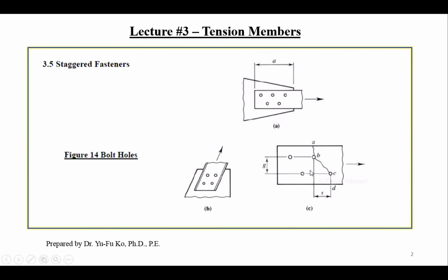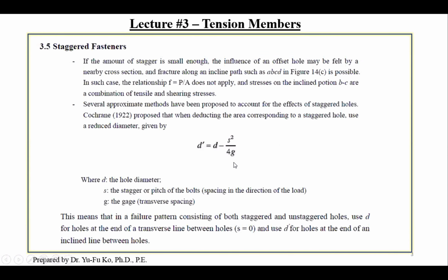But later on, maybe on Wednesday or next week, when you do more calculations, explore more examples, and I go over more theory, you will understand the overall picture. But today, you just need to know there's an approach to account for stagger hole effects. You need to reduce the diameter by this.